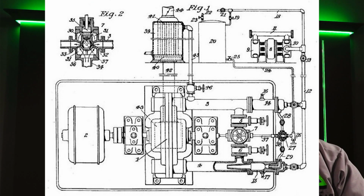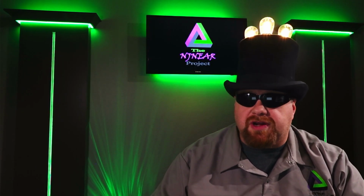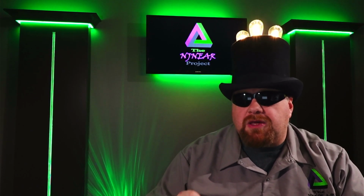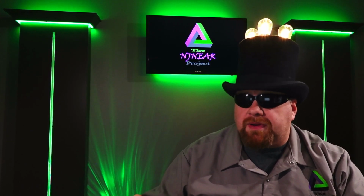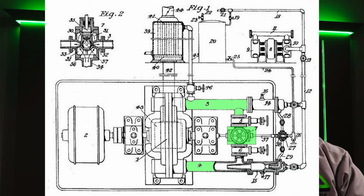When we evaluate Tesla patent 186083, there is a lot going on. Many people have said that Tesla was ahead of his time, and I find the similarities in this patent to modern combined cycle power plants very intriguing. This design was intended to be used to increase the efficiency of steam power plants and assumes steam on site. Steam enters through valve 7 and distributes it to both sides of a turbine. Inside of number 14 and the cutaway version number 15, we have combustion chambers. The steam and exhaust enter the combustion chambers together, causing the turbine to rotate.